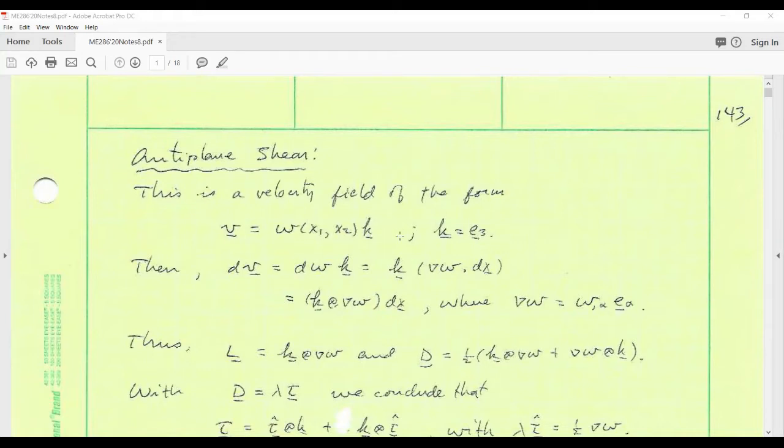So we'd like to see if we can construct a stress field, assuming, again, a rigid, perfectly plastic material. Construct an associated stress field in equilibrium, for example, from this velocity field. The first order of business is to compute the spatial velocity gradient. To do that, we use the chain rule as usual, so we can write ultimately dv is L operating on d small x.